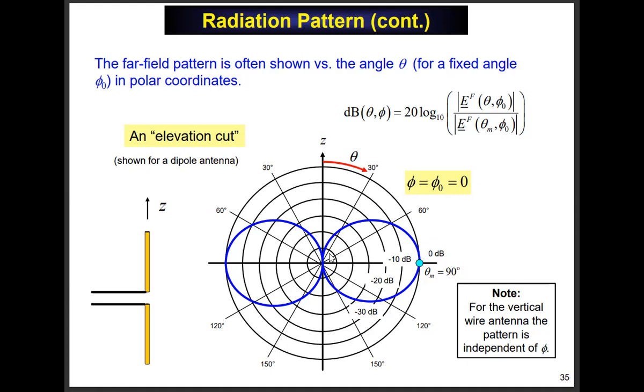Now, notice on a dB polar plot, you can never, of course, show an exact null in the pattern. I mean, if you have an angle theta where the far field is 0, what would that be in dB? So if this is 0 here in the numerator, you know, log 10 of 0, what would that be in dB? Okay, well, it's a reasonable guess, but no. So what's log of 0? Yeah, I guess a mathematician might say that, undefined.